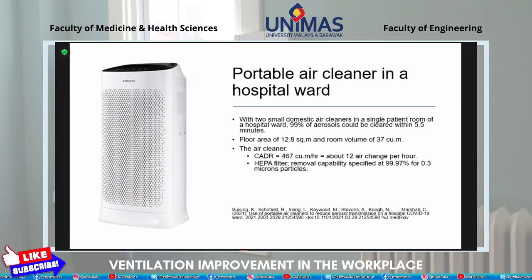So in that room, the hospital ward, HVAC professionals will consider that in a hospital or healthcare setting the risk is much higher. So in a healthcare setting, normally they will put up very high requirements for the HVAC system, better filters, better air change, and so on. So in 1 hour, the air cleaner itself can clean the air about 12 times the room volume. What happened is that in that room with 12.8 square meters of floor area, 99.9% of aerosol was cleared within 5.5 minutes only. So 12 times. But remember that this is a very big air cleaner for that room.